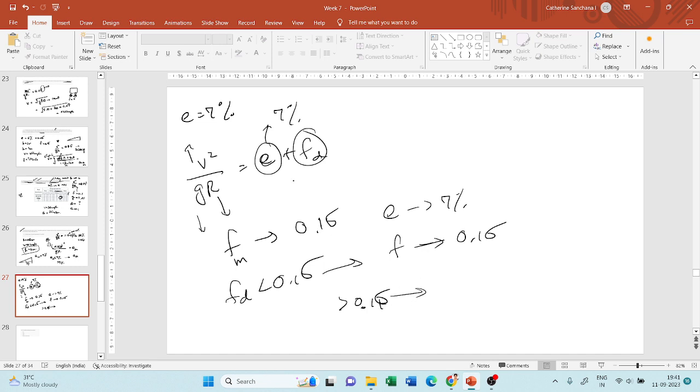So you have to limit the friction value here to 0.15, because even if you take a value more than 0.15, the road cannot provide it, okay. It is the practical difficulty of the pavement, so it can provide only 0.15 friction. So if you assume that my road has a friction of 0.2 and leave it as it is, the road actually cannot provide a friction of 0.2, right. So what will happen is, vehicles tend to skid, leading to accidents. So you should know the practical scenario of your road. It can provide only 0.15, so you have to provide 0.15.